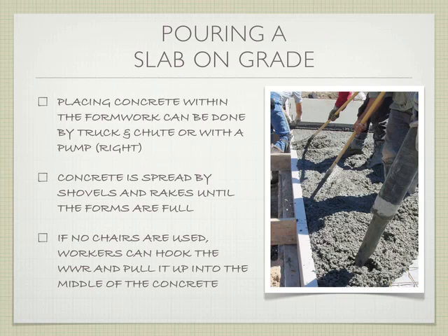Because the more distance it travels, the more likely it is to separate out, and we lose the mix of aggregates and that sort of thing. So it can be done with a truck and chute. If you can get the concrete truck close enough to your site, you can use the chute to get it to its final resting place.